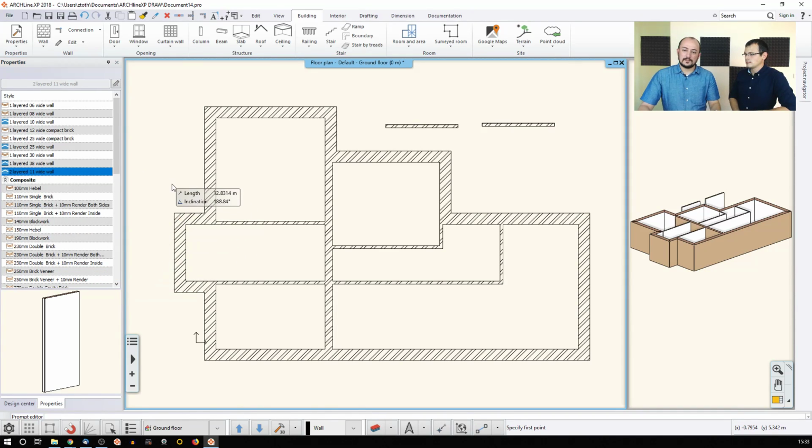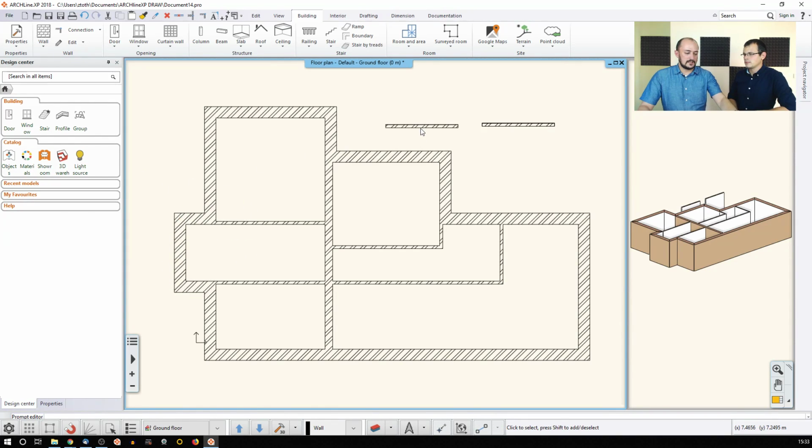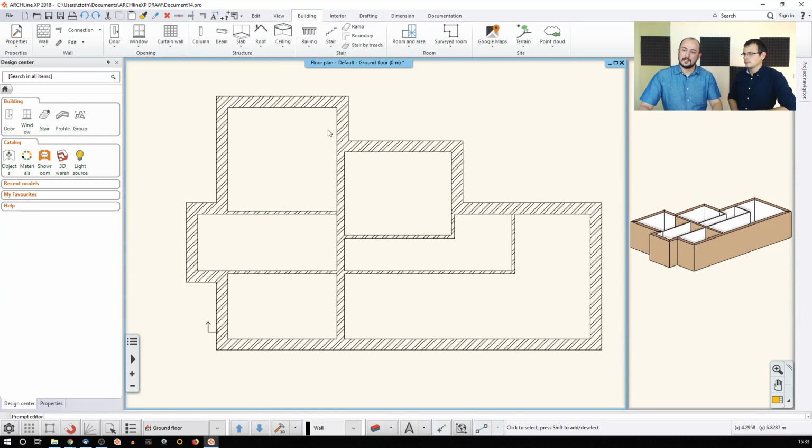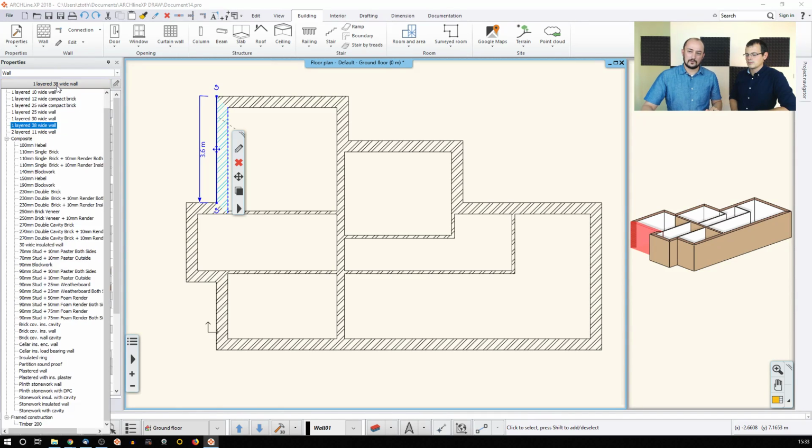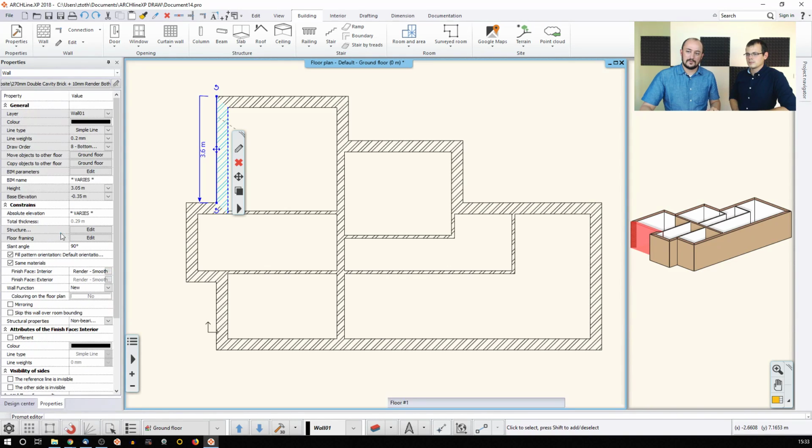Yeah, that's it here. Let me just erase these because from this point on we don't need these. Okay, this was a conceptual drawing, but now I would like to take a step further and use one of my existing multi-layer styles to exchange the existing walls to those. By default, it's very simple. You just select the wall and say it's not a one-layered wide wall anymore, but it should be something else, for example, this with rendering on it.